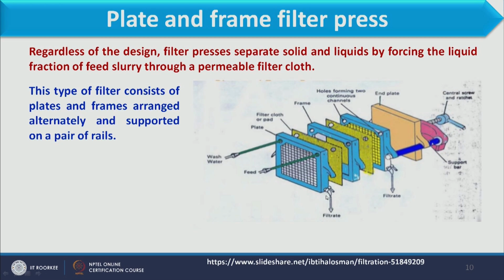In the plate, nozzles are arranged and through these the filtrate exits. Feed enters from one corner. As the plate is solid, metal throughout, the feed will not enter into it, it will pass to the filter media.